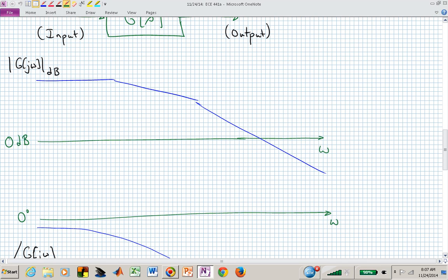And in this particular sketch, can you tell me anything about the system just by looking at the magnitude response? And now, after today's lecture, you should be able to say, yes, of course. Now, I don't have anything labeled on the frequency axis, but those bends or breaks in the magnitude tell us something. They tell us there's some factor, either a pole factor or a zero factor, occurring when we see those breaks.